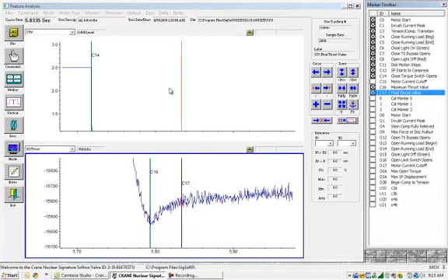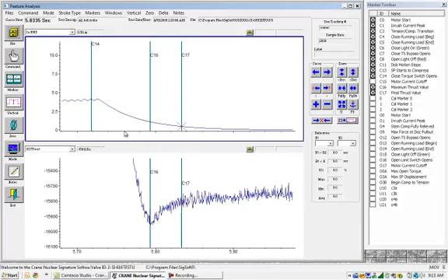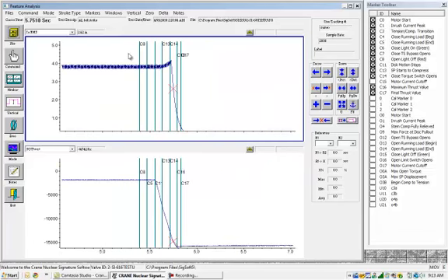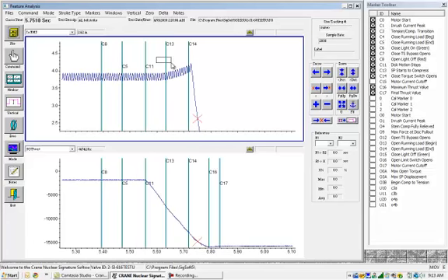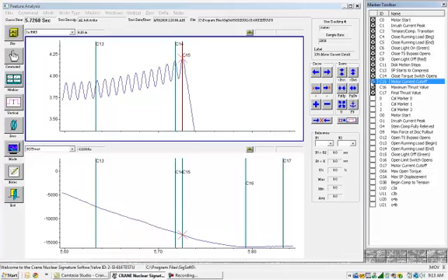And last but not least, we got to do motor stop. We were doing I sub A, RMS, and let me unexpand so you can see. Again, we're looking at the end of the stroke here, and you can see the motor stops right about there. Motor current starts falling off. I'm going to pick this last dot before it starts going down. There you have it. Those are closed marks.